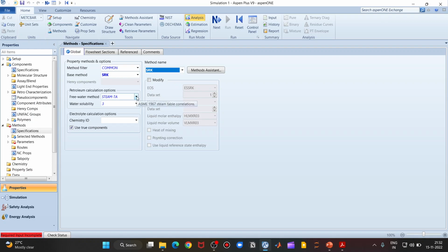If you remember from your thermodynamics courses, you had used some steam tables at given temperature and pressure to find the vapor fraction, etc. Similarly, these tables work on different properties. We don't need to go into much detail about it, but for the time being, just know that we'll be using the steam NBS tables rather than the default one. Okay, so let's click on next.